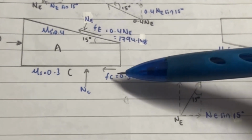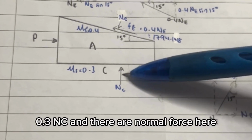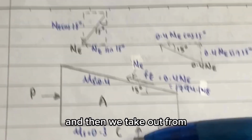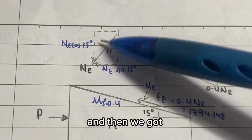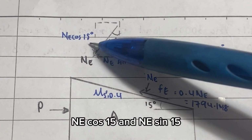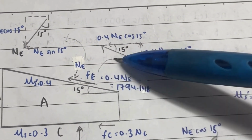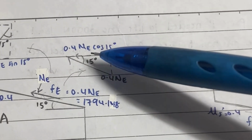For Fc, 0.3 NC, and there are normal forces here. Then we take out from Ne, Ne cos 15 and Ne sin 15, and for Fe here 0.4 Ne sin 15 and 0.4 Ne cos 15.